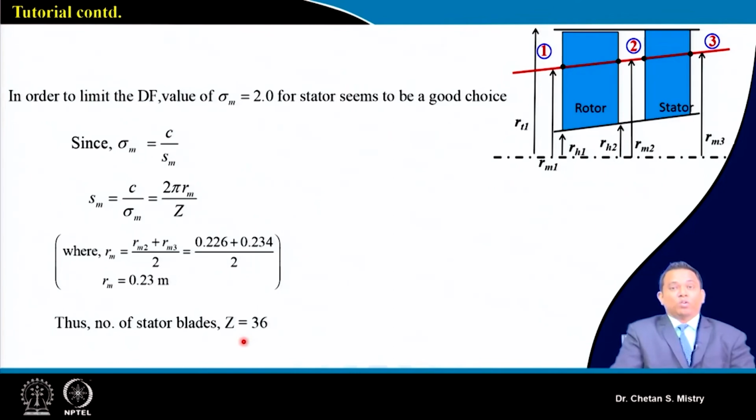Many times, as we have discussed earlier, mechanical engineers insist on having fewer blades. Again, fewer blades versus more blades is a hot discussion for the design. When we expect the weight of the engine to be lower, it is obvious you go with a lower number of blades for both rotor and stator.